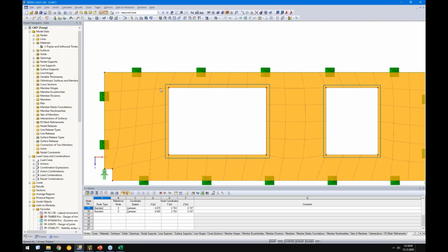And with the background that the producer does not put any glue on the narrow sides, and even if they put glue on the narrow sides, I do not recommend it as a rigid connection because of humidity effects and so on. So because of this, and we check this distortion design, what I mentioned in the presentation, the FE mesh size should be the same as the board width. So when you think about the ratio board width to board height around 4 to 1 or 3 to 1, then with a board thickness of 40 millimeters, what is used in this example, and use 3 to 1, we get 120 millimeter board width.